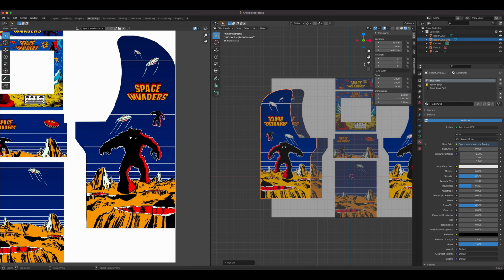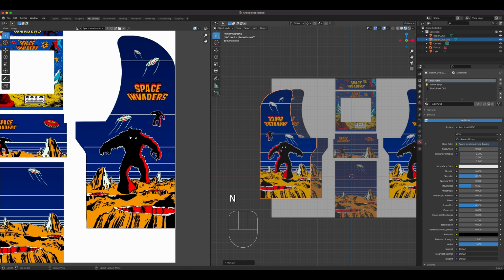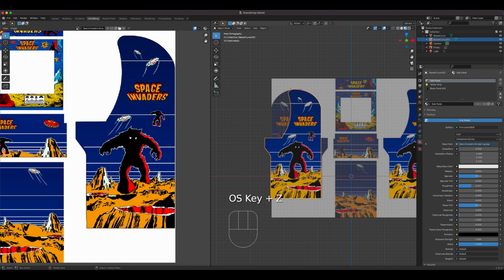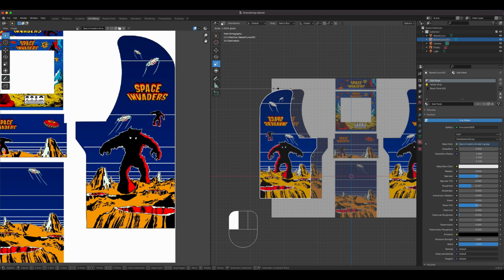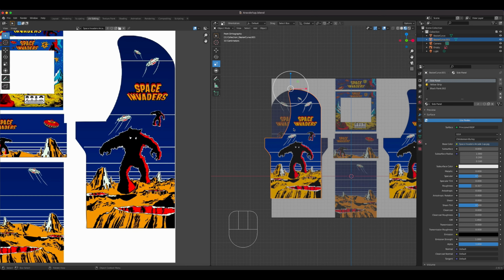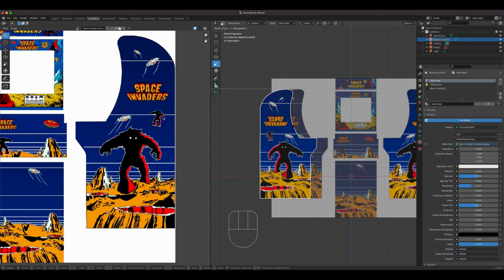Let me turn on screencast here. So S X minus 1 is simply you flip it over using the scale. So let me undo that. Undo, right? Remember, if I go like this, the scale tool along X, you go over and you basically flip it like that. So when you press S and then X axis minus 1, basically opposite but one scale. There we go.